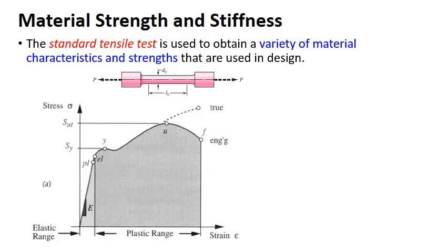And you also have the true stress-strain curve, where the stress will increase even after the ultimate tensile strength. We will see why it is so, very briefly, later. And we will discuss each of these points. What is elastic range? What is plastic range? What is this capital E? What is this PL? This is the proportional limit. What is EL? See here in this figure, PL is below EL. Is it correct? We don't have an answer for this, because PL and EL are very closely situated.